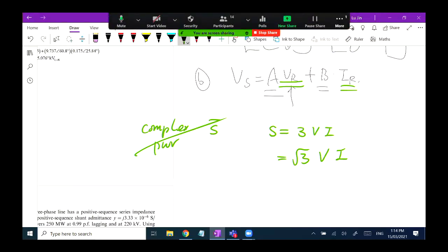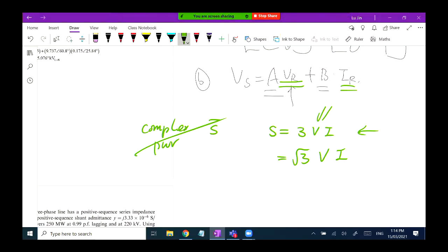So now, for the top formula here, what voltage should we use? Line-to-line voltage or phase voltage? Right, phase voltage. So here I just write down Vφ to make things shorter. It means phase voltage. In the solution, I think we are using VAN. A means phase A, N means neutral, so A to neutral means the phase voltage, same thing.